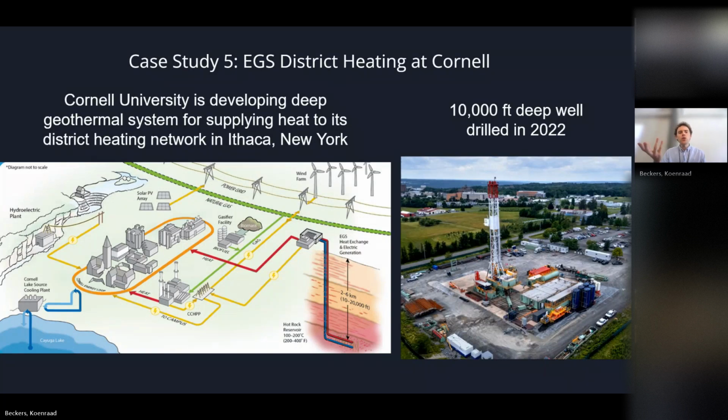So some of the values we were able to get from the CUBO well, the Cornell University Borehole Observatory well, in terms of temperatures. We know some of the rock conditions, etc. So we were able to use that information as some of the input. But then we were able to play with some of the cases, with some of the configurations. There's a lot of different examples that you can run with or without a heat pump, with or without a district heating, or how you're going to use a district heating system. So I just picked one.